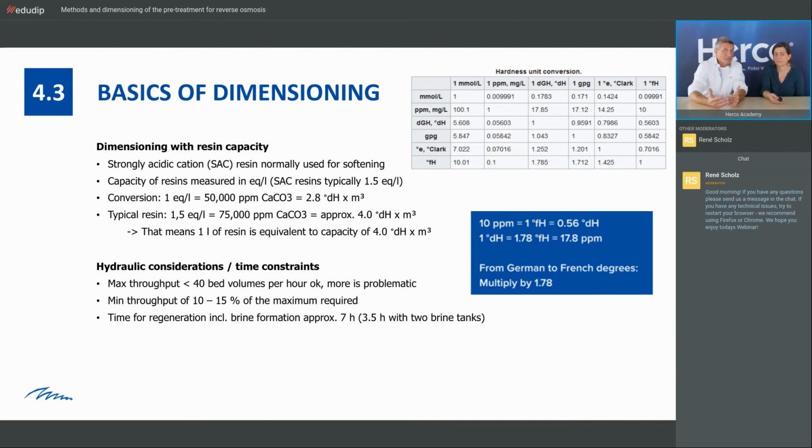The time between 2 regenerations of one resin bed is 7 hours because we are using brine tanks where the brine is made from salt tablets, and the time needed for dissolving to the maximum brine concentration plus the time used for the regeneration itself is around 7 hours.